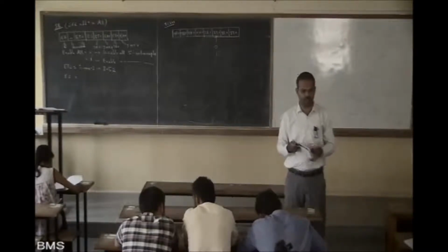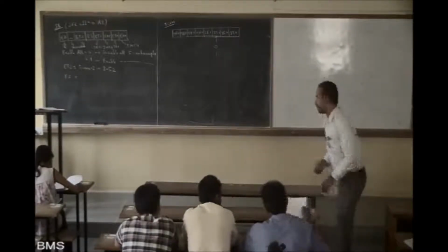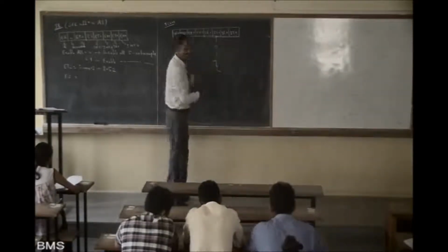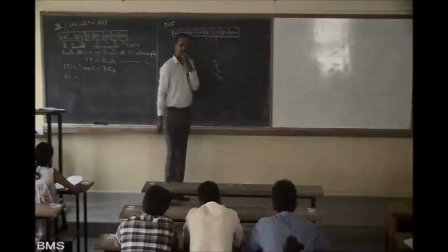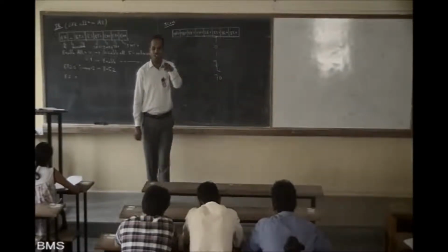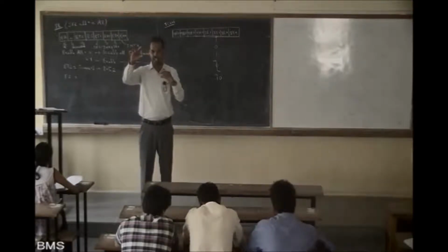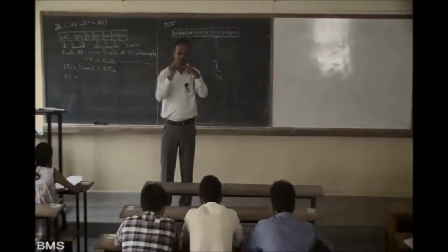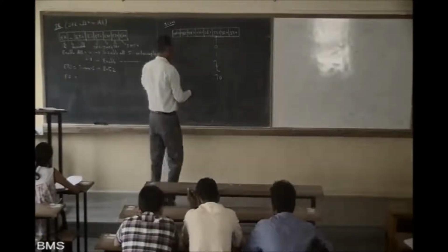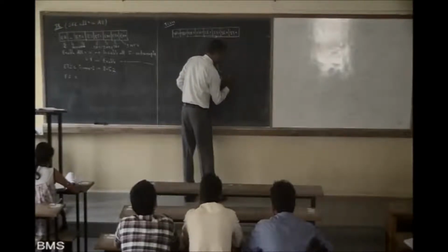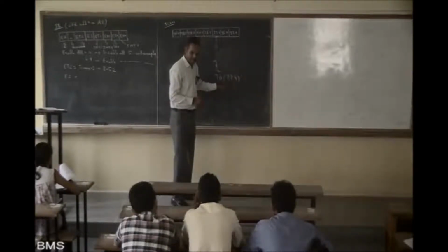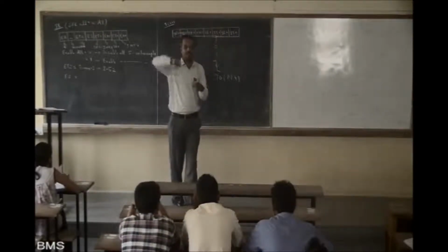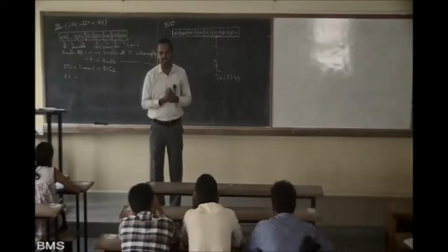For counters I am saying, for both of these, when I make this IT1, they will act on the negative edge, particularly T0. You said clock, right? It is not exactly a clock. Clock for the counter, yes. From where is it coming? From the external source onto the pin T0. What is the pin T0 number? P3.4. Onto this pin, if there is a negative edge, then this will take it as one clock.